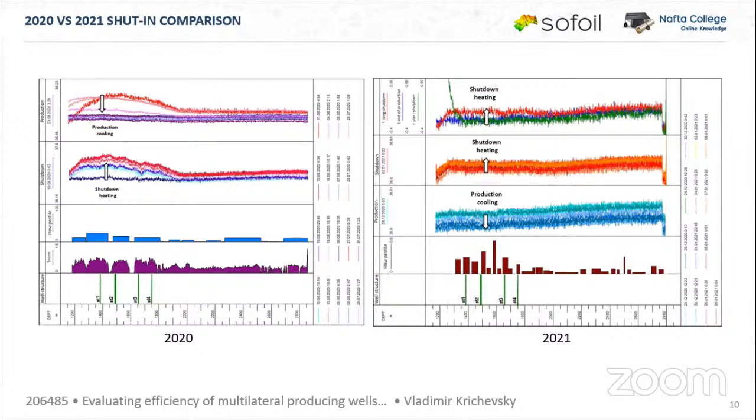And if we look thoroughly, we may see that during these several months of production, the inflow redistributed a bit. And we now have more inflow from the main wellbore compared to the side tracks. Well, I think that's pretty natural, of course, because the side tracks are starting to interfere, and some of them are, of course, losing production. The pressure is going down faster for some side tracks, and that's actually okay. But the main wellbore starts to produce a little bit more by the end of this appraisal production period. Okay, so these would be the results of the DTS.